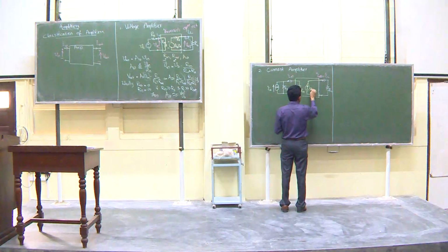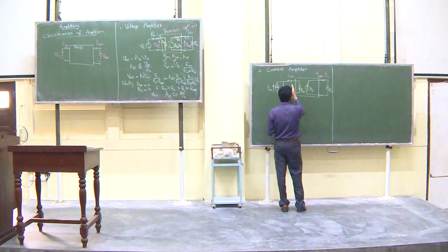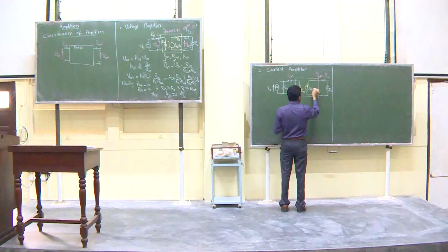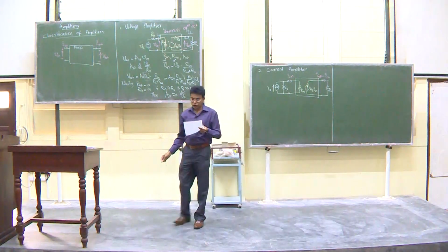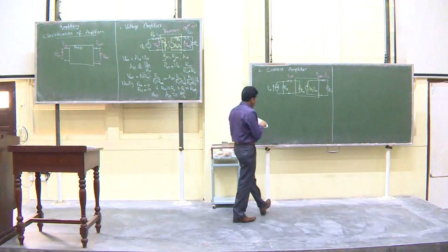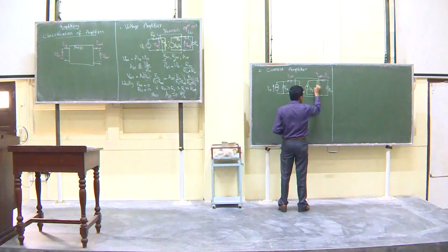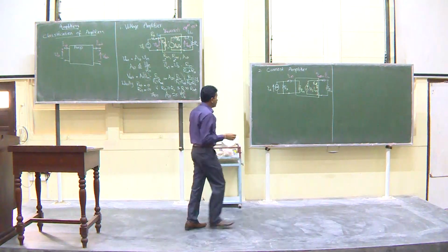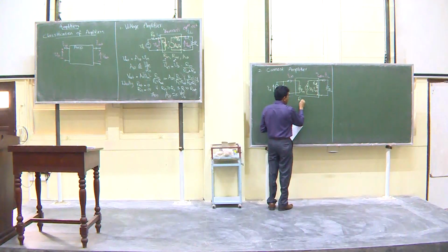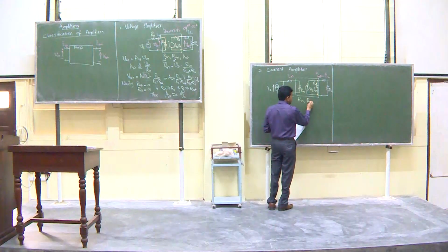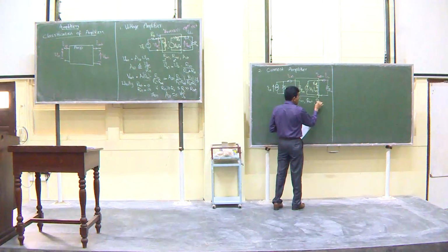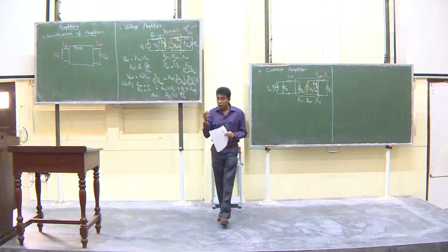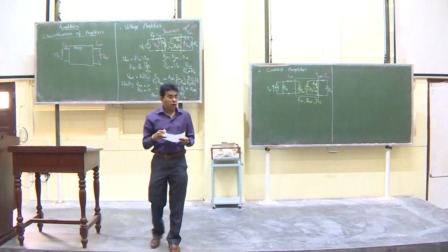This value is AI, that is the constant that defines the current that is coming in and current going out, times I in, right. So, that is the relationship. But at the same time, you also have a Norton's equivalent resistance, which we call R out. Okay, so the three things again we have are R in, R out, and instead of AV now we have AI. These are the three things that fully characterize this current amplifier.